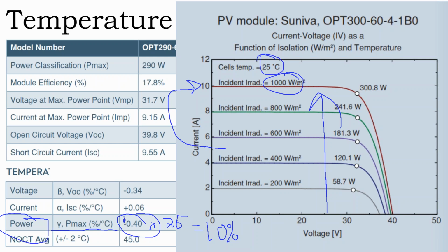And so the solar array temperature is way off, the amount of sunlight in the air is way off, and so it's very hard just to look at a module spec sheet and say, okay, I know how much energy this is going to produce a year. Inevitably, you have to go and do a computer model that calculates it for every hour of the day based off temperature, based off performance degradation. PVWatts is doing that all behind the scenes.